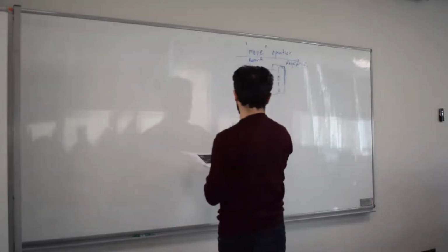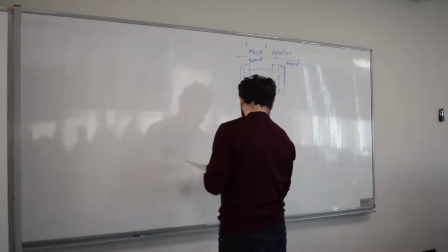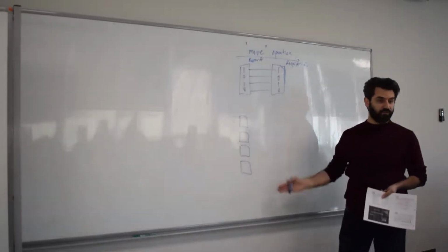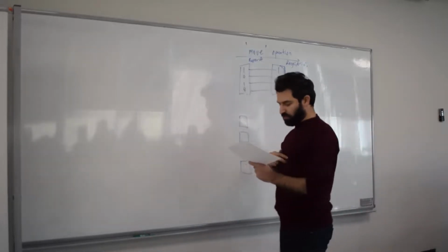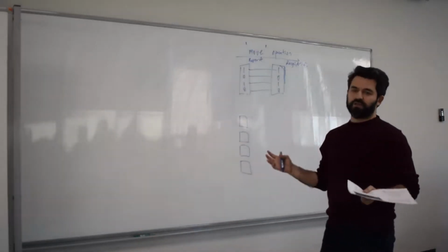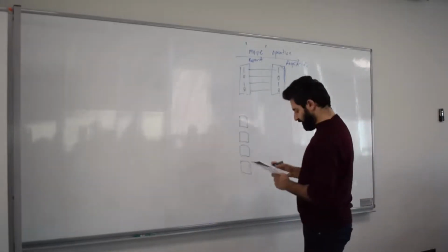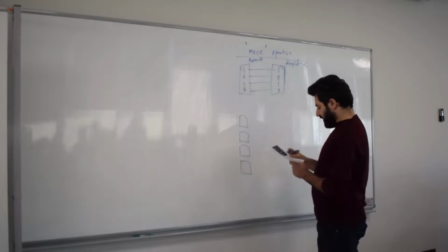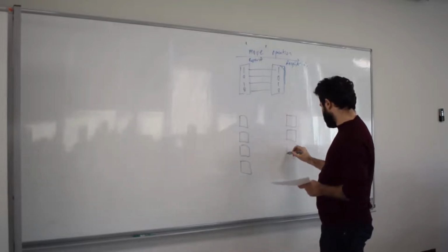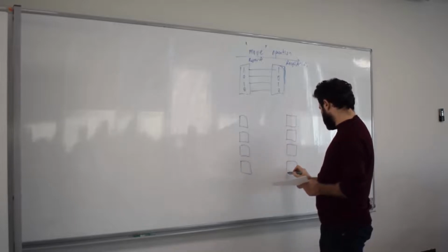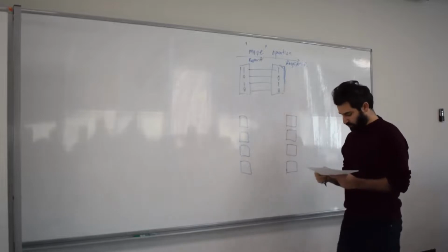The inside is not very sophisticated. You got, as you can expect, 4 flip-flops. Each one stores only 1 bit. And just for simplicity, I'm going to use D flip-flops. So these are all D flip-flops. Then I have another set of 4 flip-flops. These are the destination flip-flops that I am transferring my information to.